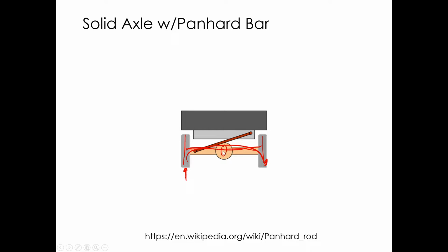And that's one of the reasons why the internet meme about Mustangs running over people at car shows actually has some truth to it. It's because Mustangs had solid axles until just a few years ago. I think 2015 was when they did the redesign, and they went away from a solid rear axle to an independent rear suspension. Having owned a couple of the solid axle Mustangs, yes, if you don't know what you're doing and you hit a bump near the limit on the rear axle, it can upset it, and the rear end of the car kicks out quite a bit.